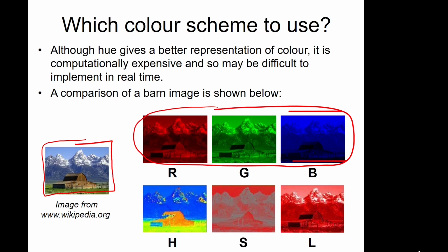If on the other hand you convert it to HSL, then you can use the H component to look for a very bright orange feature in that image and head to that. So sometimes HSL has the advantage that you can extract certain colors from an image, the downside being the processing time required.